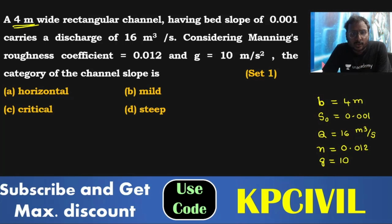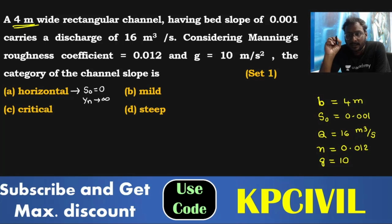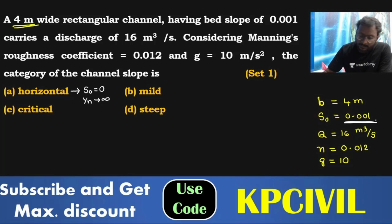Category of the channel slope is. So if you want to consider the category of channel slope, as per the given options, for a horizontal slope you consider S naught is equal to 0 and normal depth Yn is equal to infinity. S naught is given as 0.001, so it is not horizontal. Neglect it. Option A eliminated.